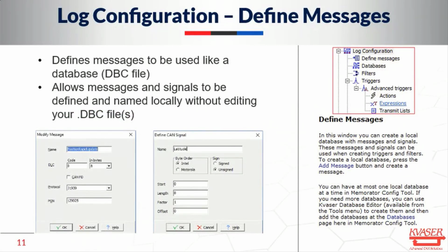So, defining messages. As I said earlier in the presentation, you have to define a message in order to set triggers and filters according to that message, or to set triggers and filters at all. You don't set them on raw CAN data.